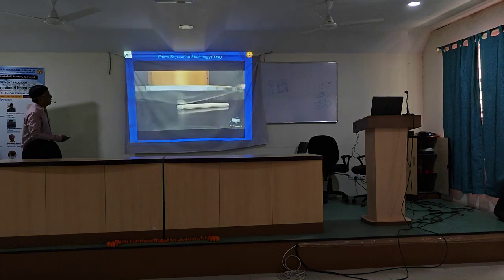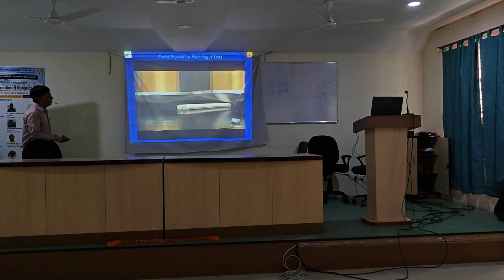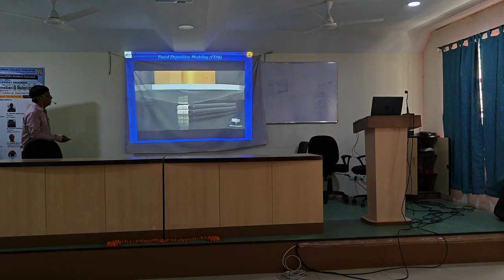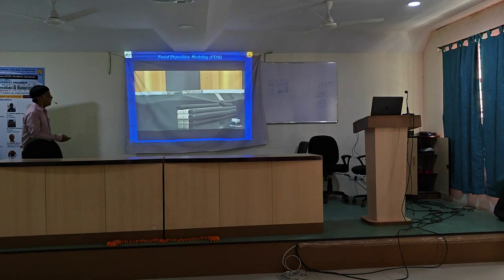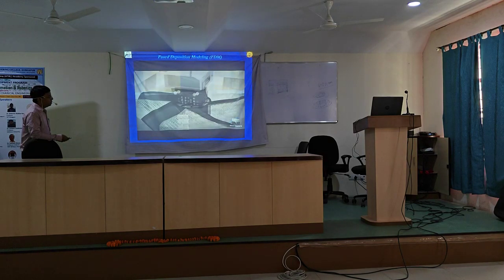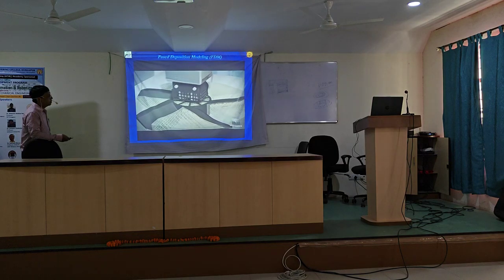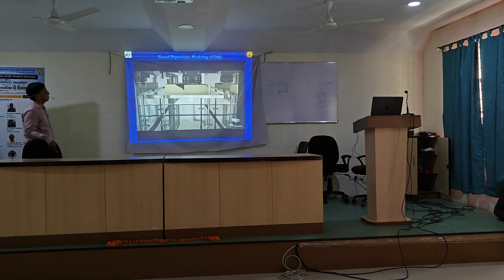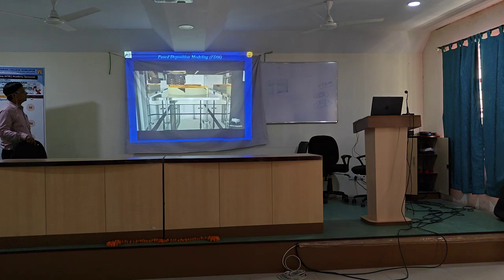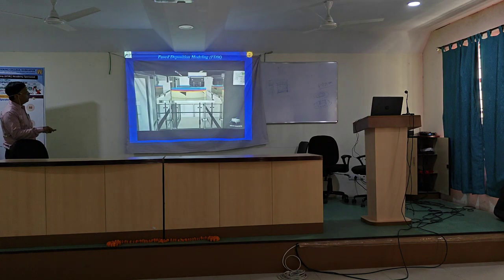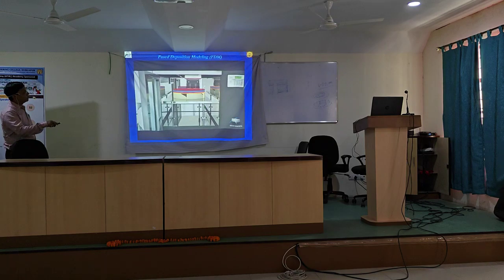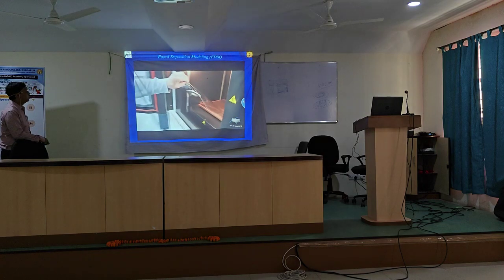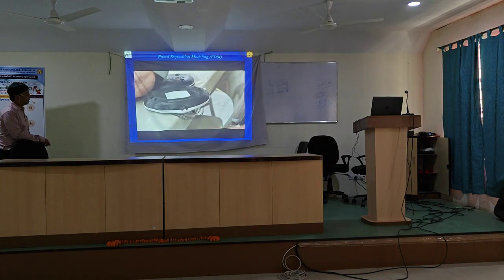The extrusion nozzles precisely lay out the material, and support is laid on the preceding layers. It is an exaggerated view. The white color is the support and the black color is the build material overhang portion. The nozzle continues to move in the horizontal XY plane while the build platform moves down. Once one layer deposition is over, the build platform is lowered by one layer thickness, through axial movement of the platform or of the nozzle, and you get the next layer.